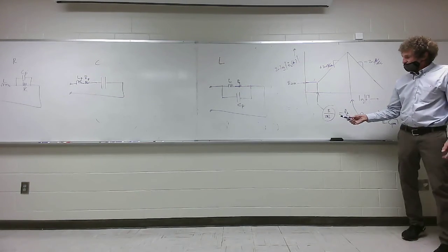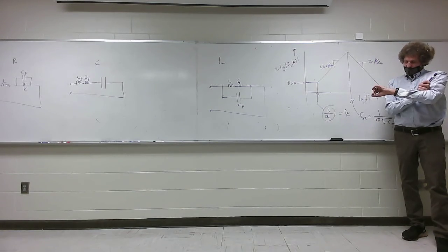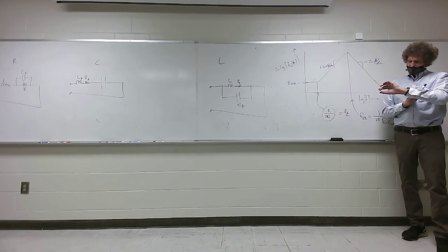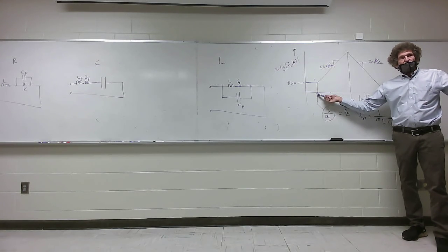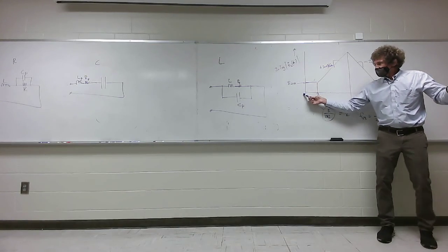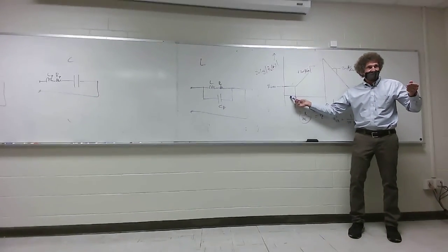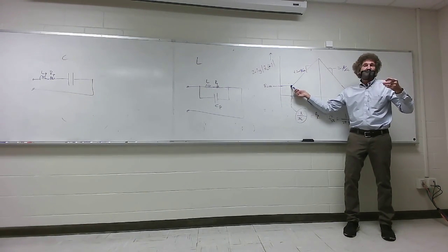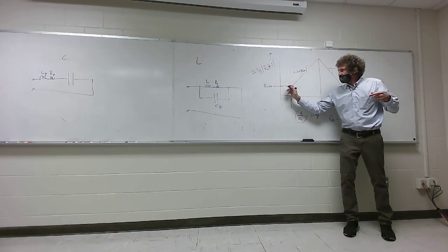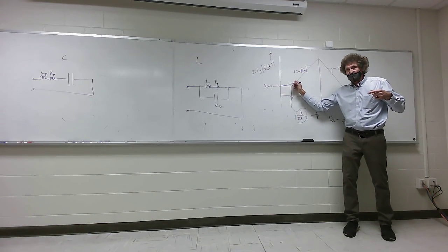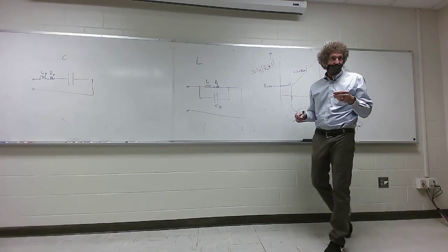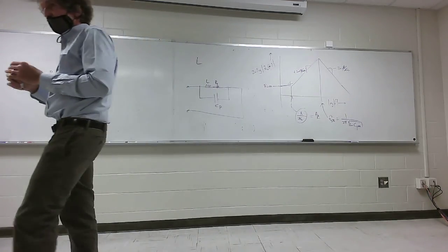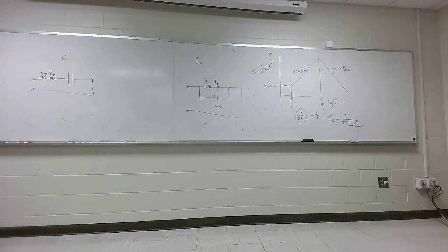Now, the reason I want to just comment on there before you go is this. Hear me. You know how I talked about resistance of wire being a function of frequency, right? Well, as you're changing frequency, that resistance is changing. The DC resistance down here is different than the resistance at this point. So if you actually get raw measurements, the point right here isn't as sharp and crisp as you'd expect. That is because the actual AC resistance of the wire is increasing as frequency goes up.